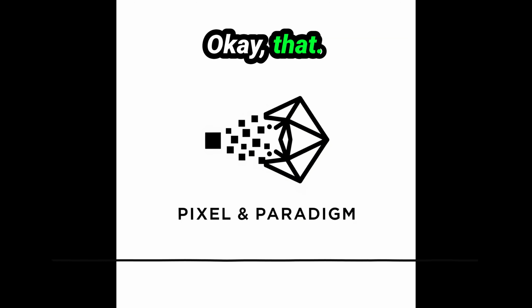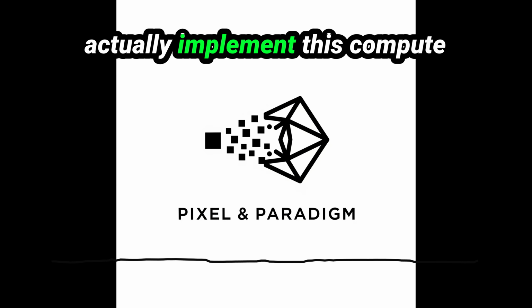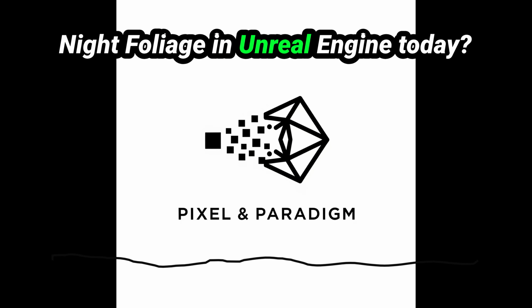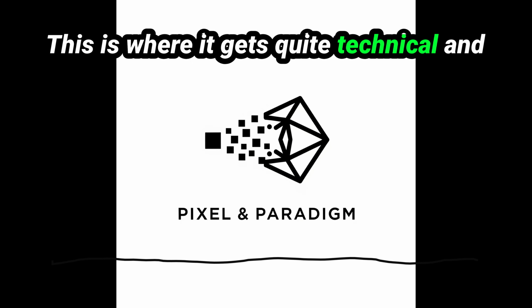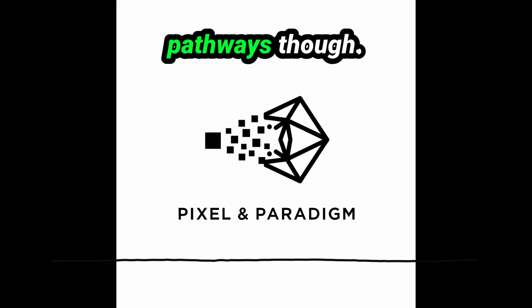Okay, that sounds powerful but complex. What are the potential ways you could actually implement this compute shader-driven bone animation for Nanite foliage in Unreal Engine today? This is where it gets quite technical, and honestly, it's much less documented and standardized than setting up WPO. There are a few potential pathways, though.